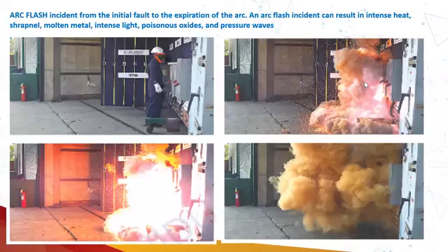that equipment failed in such a way that it caused an arc flash. So determining that the equipment is under normal operating condition is a challenge. 70E does allow that if you have determined that the equipment is under normal operating condition, you can just operate that particular equipment. Then there is no requirement of wearing any personal protective equipment, and there is no requirement of an arc flash boundary as well.